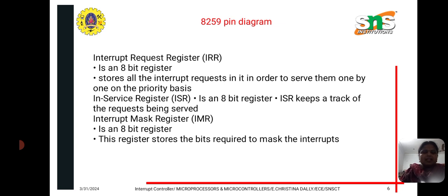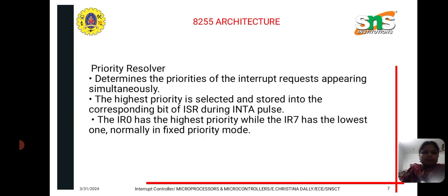At the same time, the in service register is an 8-bit register. The ISR keeps track of the request being served. The next one is the interrupt mask register. It is an 8-bit register, and it stores the bits required to mask the interrupts.